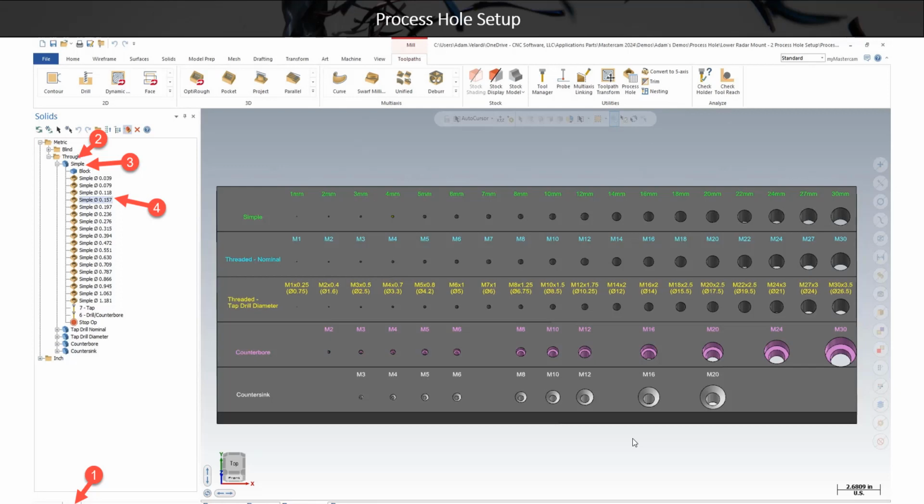So for instance, create a template file like what's shown on the screen here now, and you could create processes on this. Your template file is broken up into different toolpath groups, and whatever you name the toolpath group, that's how it'll appear when you run process holes. So each type of feature you'd make would have a different toolpath group with a name on it, and then you pick that file and it would find matches and show those.